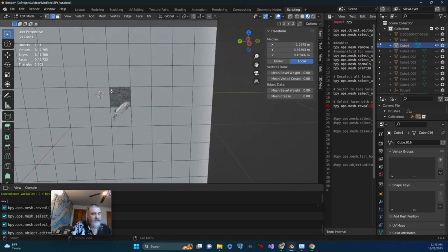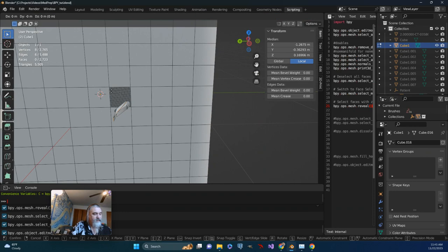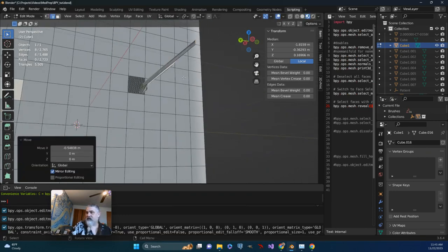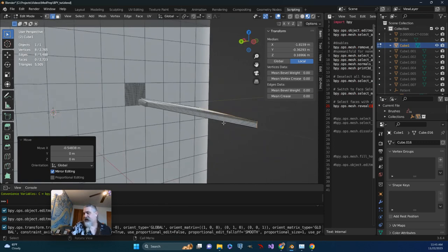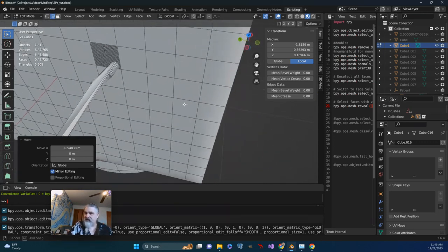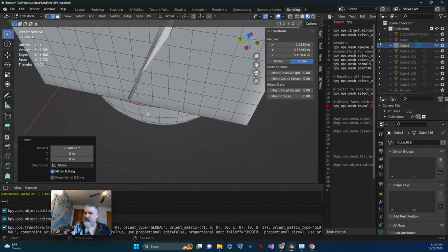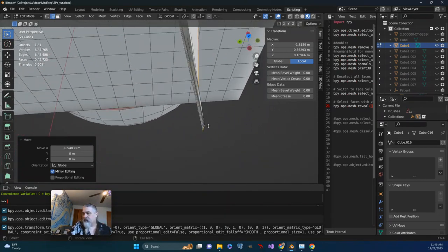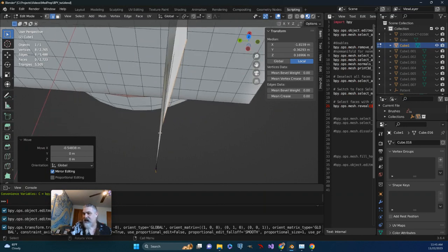Basically what's happening is, if I extend this out, that edge is getting so thin that if we were to try printing it, it just becomes razor thin. And at some point, probably back here, the printer can no longer print and maintain that edge. It got too skinny to be printable.